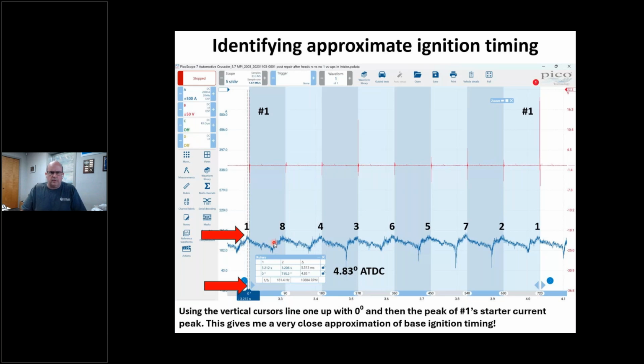It's a 10 beer story, and we don't have enough beer here to talk, but basically what happened is they installed an engine in this boat. It ran for a few hours. The customer brought the boat back and says, hey, this thing doesn't start. So what does the technician do? He checks for spark. He's got it. He checks for fuel. He's got it. He takes a fuel sample. It's not full of water or anything else.